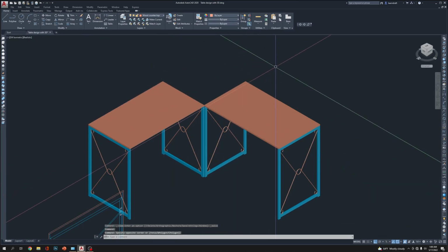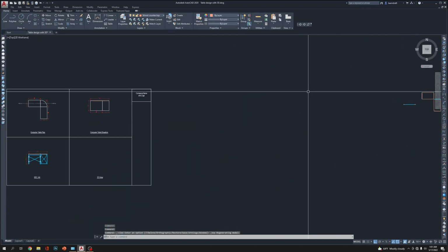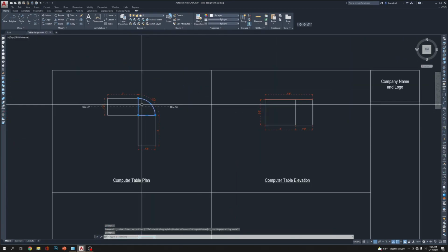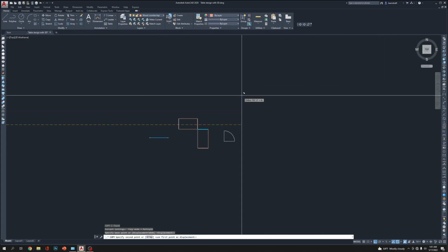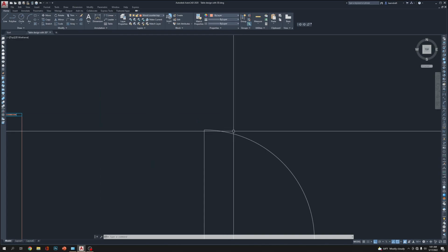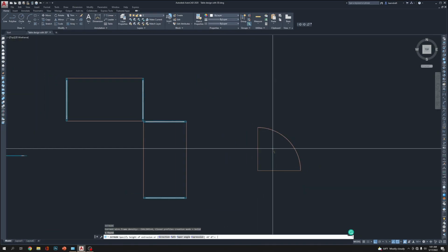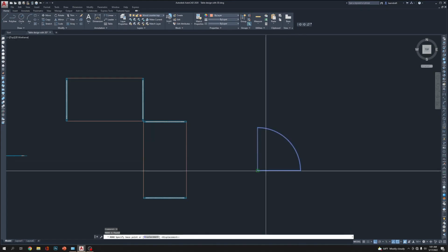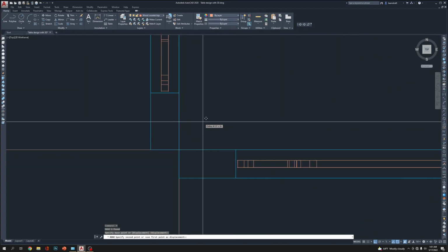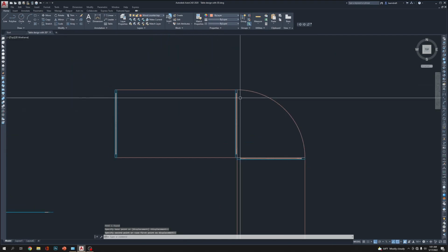Okay, that piece of wood, we're going to go to wireframe again, go to the top view, go to this piece, CO, enter, click here, bring it there, extruding this one to 0.5, enter, select it, click from the corner, take it to this corner, and here you go.